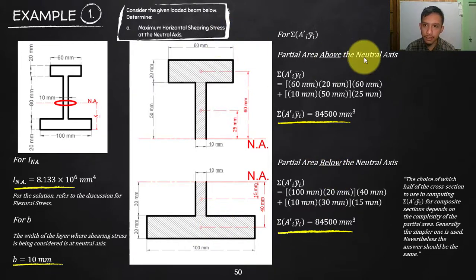Okay, using the top, the area. By the way, we established before that the y bar is 50 from your base and then 70 from the top, and of course that 60 is on the centroid, that 40 is on the centroid of the rectangle. And of course, if that is 50 going here, and then minus that 20, the remaining is 30. So half of that to get the centroid of this rectangle here is 15. And again, if that is 70, subtract your 20, the remaining will be 50 divided by 2, that is 25. So you have already the dimensions here in the figure.